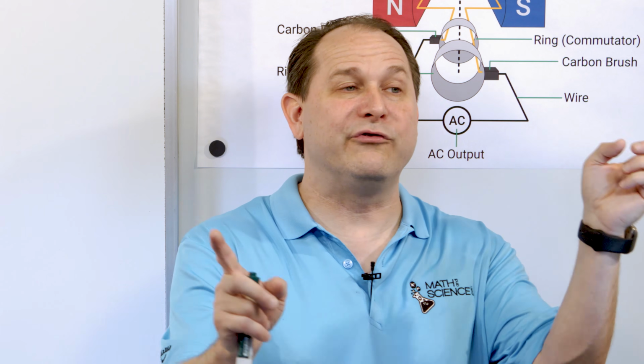We're turning a coil of wire in a magnetic field. It's exactly the opposite of a motor. With a motor, you turn on the electricity and then you force the thing to turn inside of the magnetic field. For a generator, you do it backwards. You turn the wire through some mechanical thing like a hydroelectric or nuclear plant, and then that generates what they call an EMF, electromotive force, which is the same thing as a voltage here.